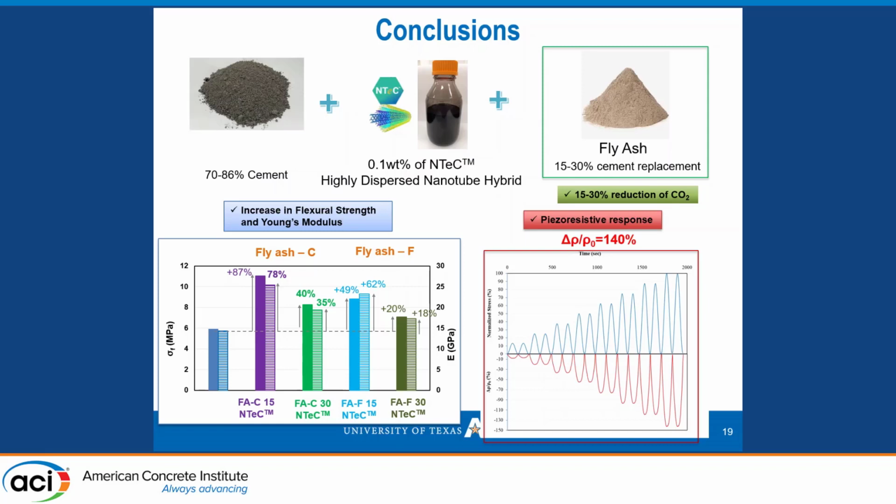It is really important to note here that while the mechanical properties are dosage and type of fly ash dependent, the piezoresistivity response was found to be independent. It doesn't show the same trend as the mechanical properties. All the mixes tested showed a really high piezoresistive response, and from that we can understand that these mixes can be used as piezoresistive sensors for strain, stress, and crack detecting purposes.